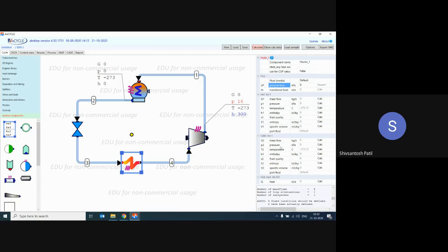Now go to the outlet temperature and make it fixed. For example, -15, -14, I write down -14. After evaporation is done, the temperature is still -14. Because after expansion we'll get a very low temperature, but after getting heat, it still goes to -14. After expansion, I think we'll get -50 or something lower in that area. Now come to the -14.